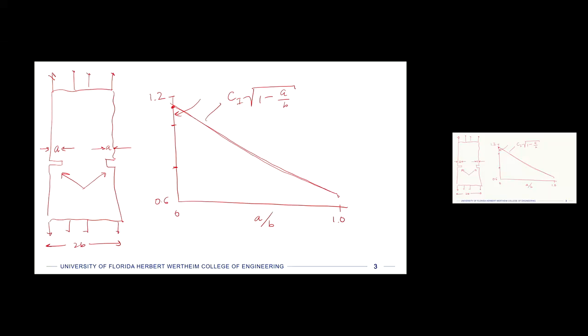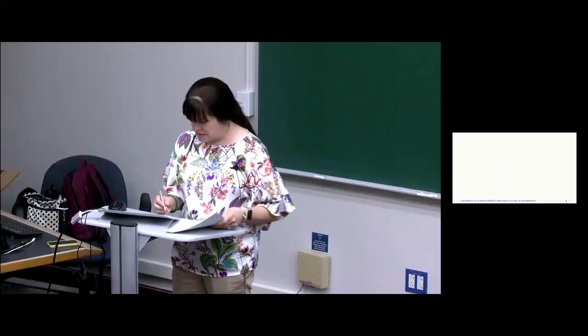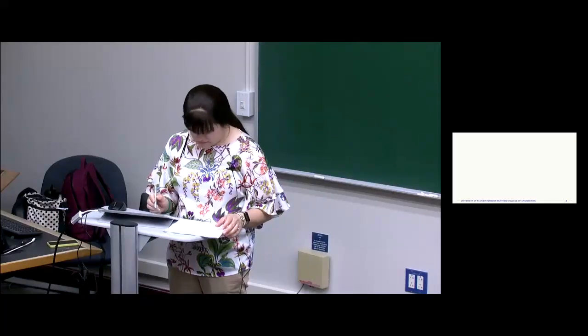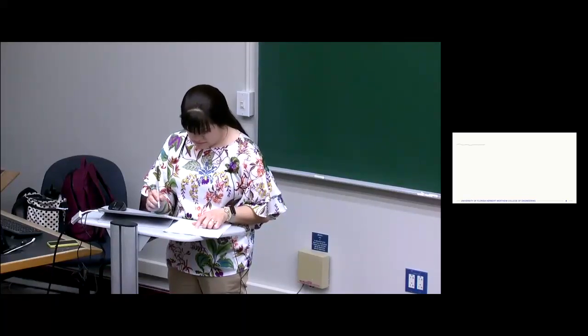And one of the most common situations that occurs is an edge crack on one side because of a bending loading, right? So I'll draw up this schematic here. So we'll have a plate with only one edge crack of length A. And instead of having a tensile force on this, we're just going to have a pure bending moment that's symmetric on both sides.